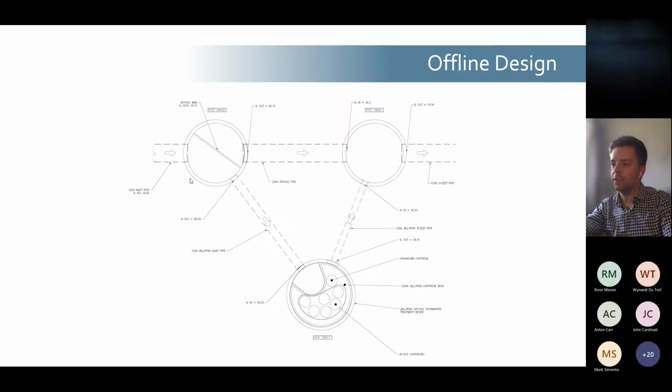It depends on the arrangement and the project and the scope. If you adopt this general arrangement that is shared here, whether it's a JellyFish or a StormFilter or a Cascade that's placed offline, we can provide you with the driving head level of the treatment device, and that will then dictate the level that the weir is set at. In terms of the design of the weir, if you want to increase the length of it to reduce the head losses across that structure because of upstream considerations, that's something we can talk to, but the design of which is left in your hands.